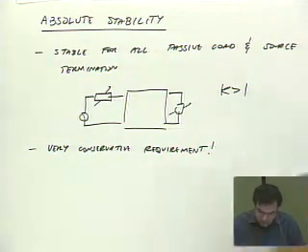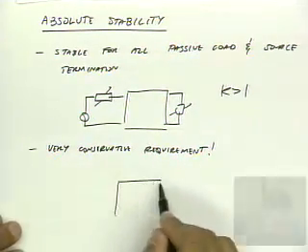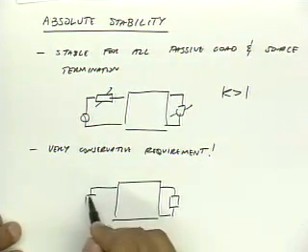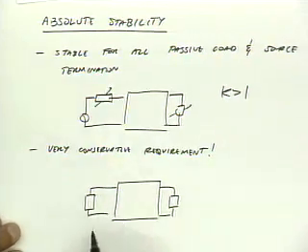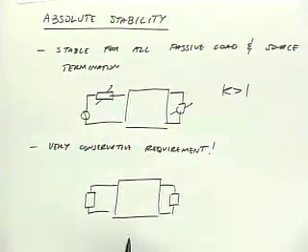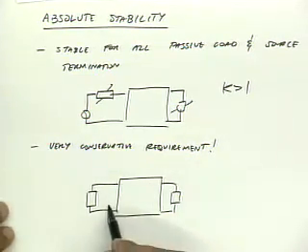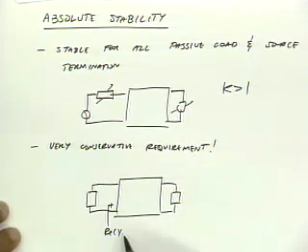Well, what's also interesting is if I have something that's not stable, so let's say I have a 2-port that's unstable, and I want to stabilize it. What's a really easy way to stabilize this 2-port so that I make it unconditionally stable? Exactly, add positive conductance. So remember, instability means that if I look into here, the real part of y in is less than 0.